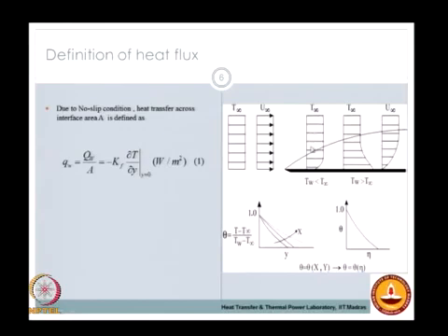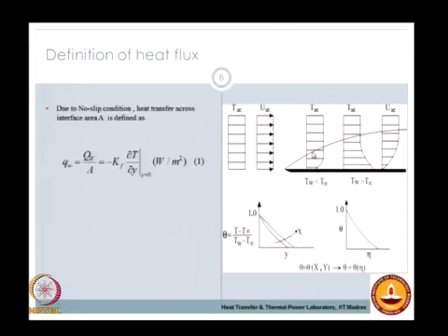This boundary layer is attributed to the no slip boundary condition at the wall, where the fluid has to take the velocity of the solid, which is stationary, and therefore the fluid has to be at rest. Essentially the lower layers of the fluid have lower momentum compared to the higher layers of the fluid, and this gives rise to the concept of the boundary layer. If you look at the profiles of velocity, you can see that they keep changing, the gradient of the velocity being highest near the leading edge, and as you go downstream the gradients become more and more benign. Similarly, associated with the velocity gradients, you see the development of temperature gradients.